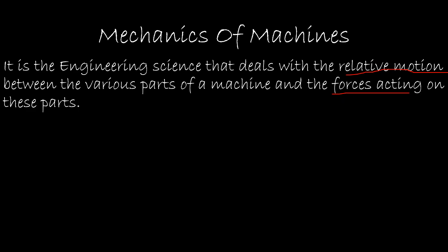When you talk about constrained motion, it's the motion of a mechanical component whose movement is limited towards a definite path or direction due to the presence of a constraint. So let's take a mechanical component like gears. When gears are in a working machine, they can't move in any direction or path they want. They move in a definite or specific path or direction. Why? Because there's the presence of a limitation, or what? A constraint. Something is limiting it from moving in any path or direction it wants. That is what we call constrained motion.